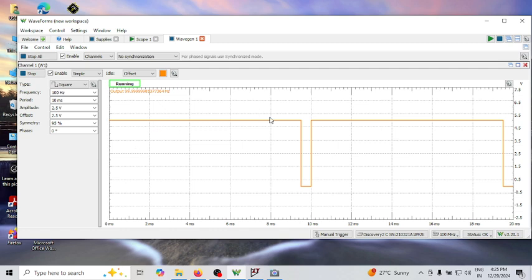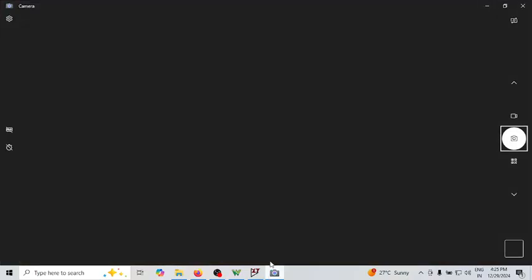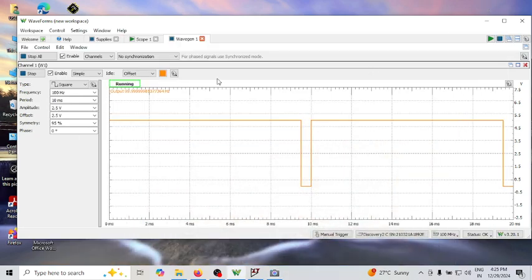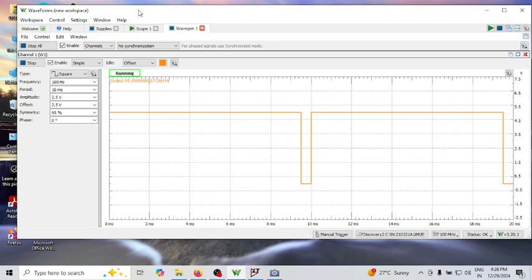You can see now this is typically the waveform that I expected, what I wanted here. You can see I am getting a signal something like this. This is 0 to 5 volt with a very small off time; the on time is 95%, the off time is hardly 5%. So this is the type of signal that is applied to pin number 2 of my circuit. So you can just have a look at it.